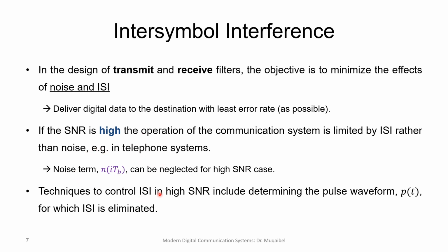Techniques to control ISI in higher signal to noise ratio determine the pulse waveform for which ISI is eliminated. So we are looking at pulse design. We'll assume that we have no problem with the noise and would like to get rid of ISI. And that's called pulse shaping.